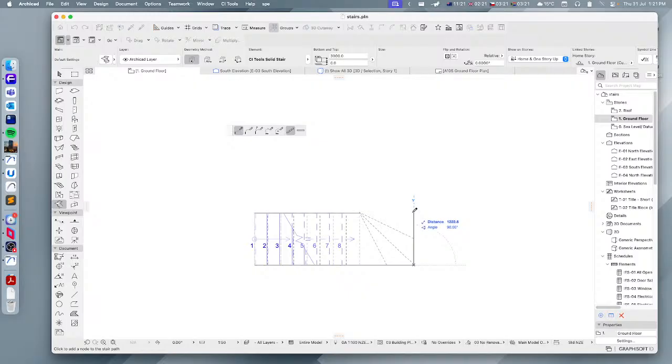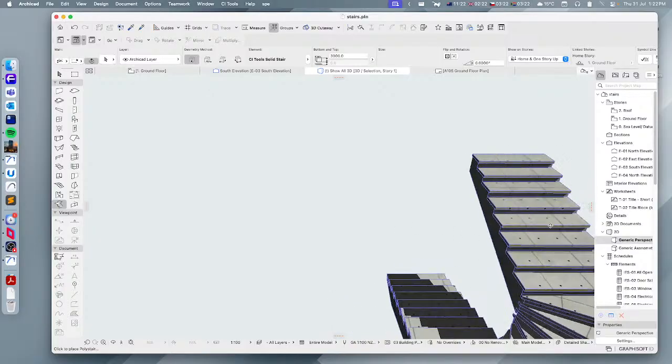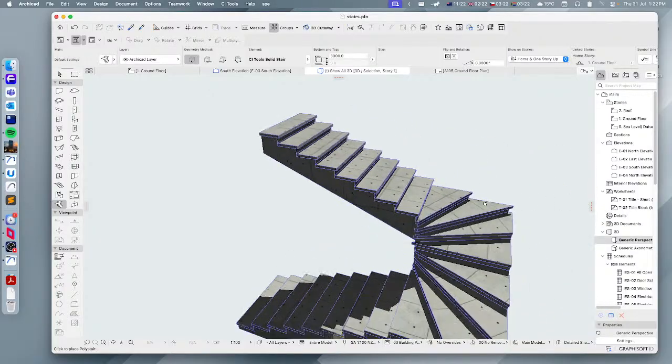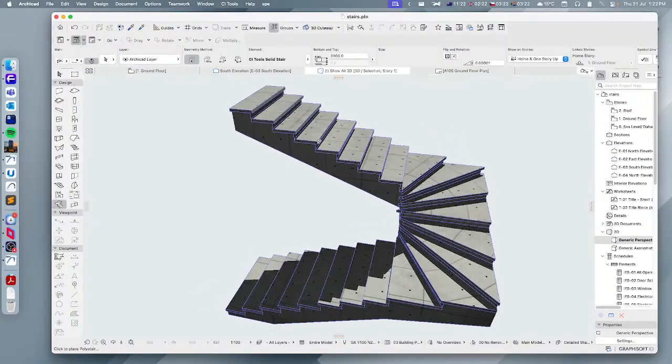Okay, we're going to just over 1200, and we can change those sizes later if we need to. Just over 1200 here, and turning the corner, and then we will stop very early there, and then we will go straight again, and I'll just equal it up with our beginning point. There we go. So now we've got a straight flight. We wind around the corners up to the top there, and then we go straight again.